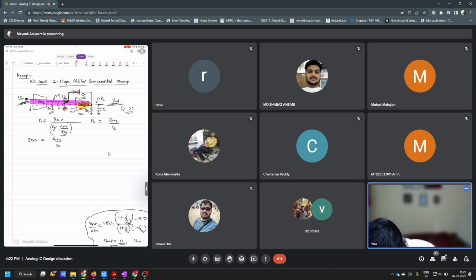Okay, so what will happen at zero frequency is that basically at zero, this current which is coming from here, okay, and this current which is coming from gm2, this will be of opposite signs, okay. This current which comes from cc right here will directly go inside gm2. It will not be going anywhere into cl or g02. Did you understand that? At zero frequency, all the current that comes from cc will directly go inside gm2 and therefore will not generate any voltage. So that is why we get a zero. Is that understood now?